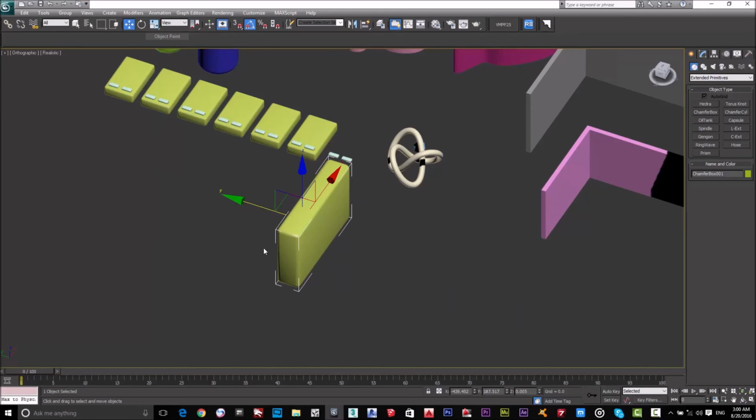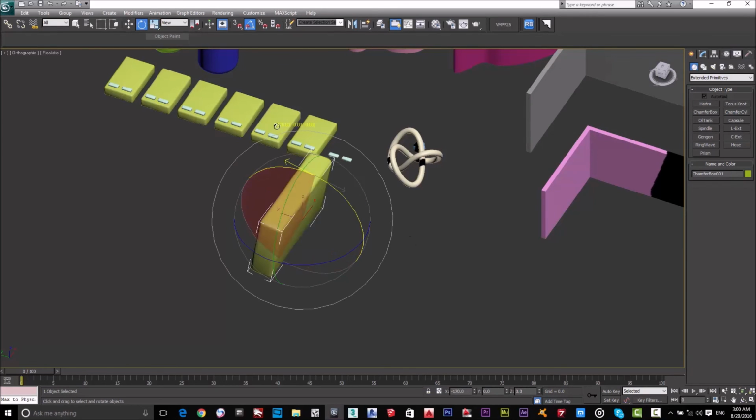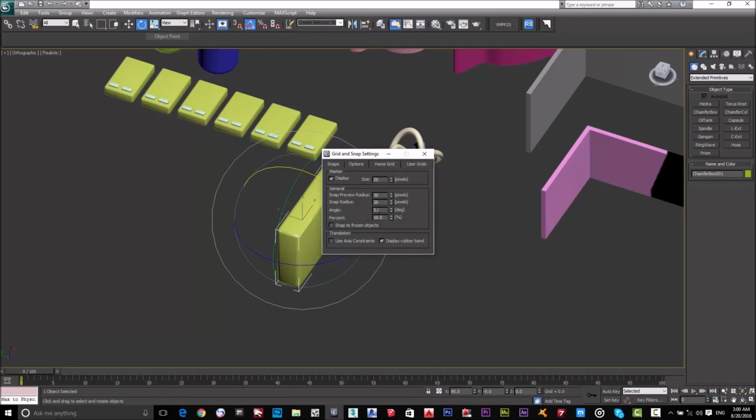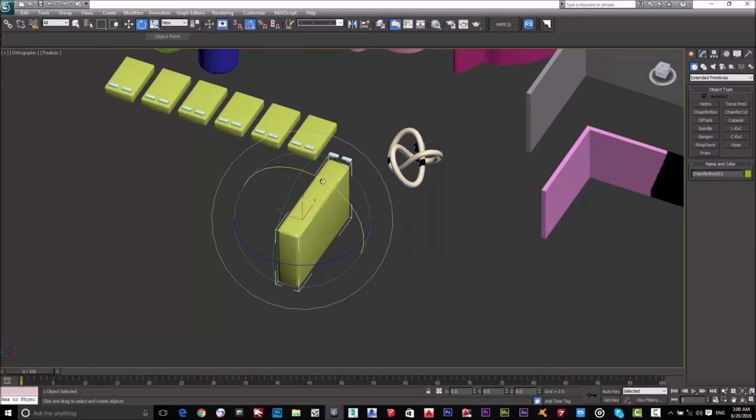And I have another thing, which is rotation, also through the keyboard. As I explained, if I want it to move each step 5 degrees or 10 degrees or whatever, I have to activate it by hitting A on the keyboard, then going here and controlling this third choice, either 5 degrees, 10 degrees, whatever, even 90 degrees. Then hit enter, and if I take one step now, it moves 90 degrees, as you can see.